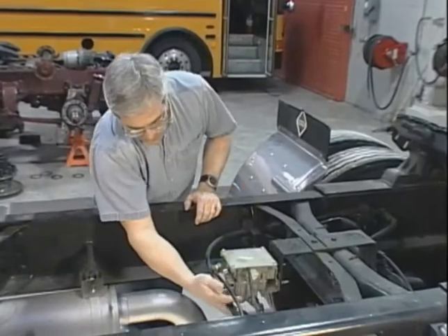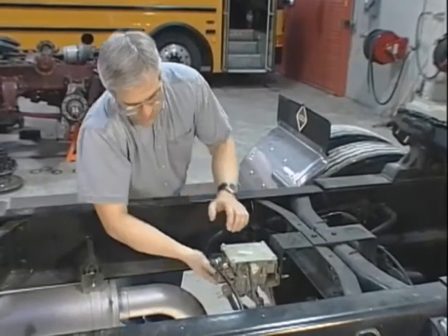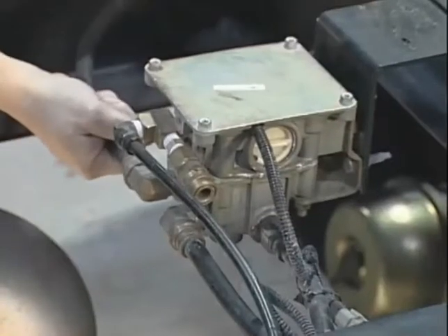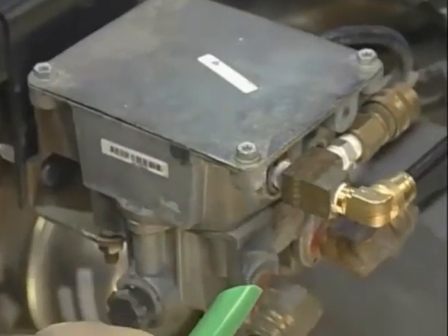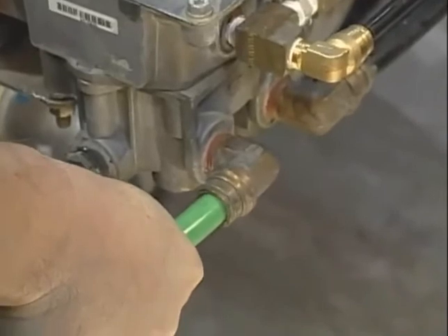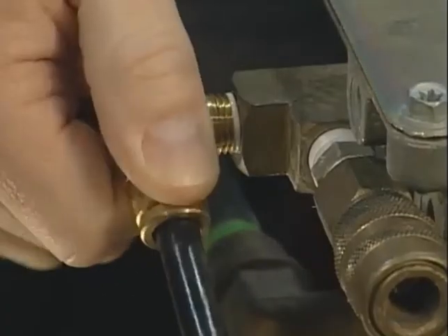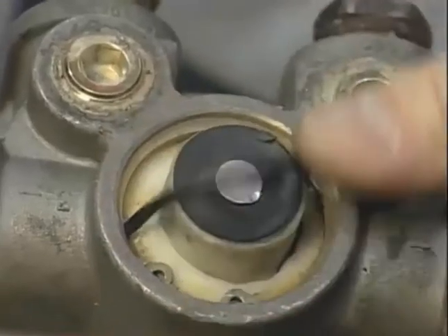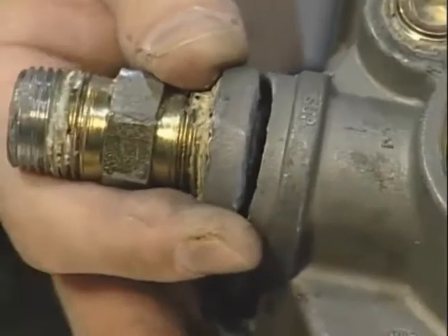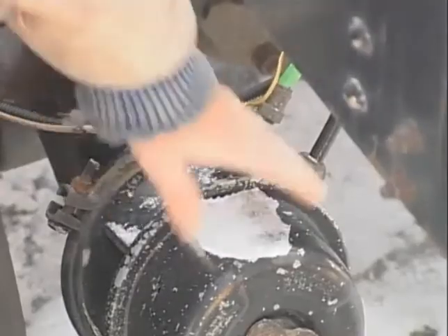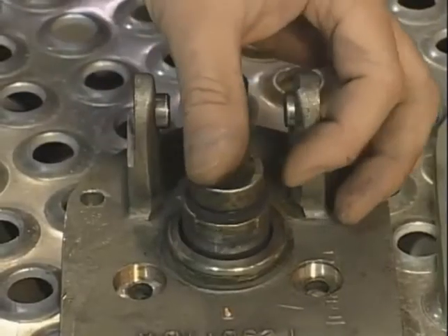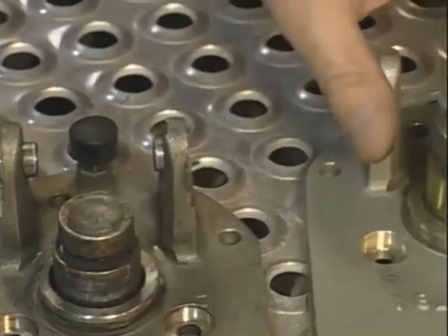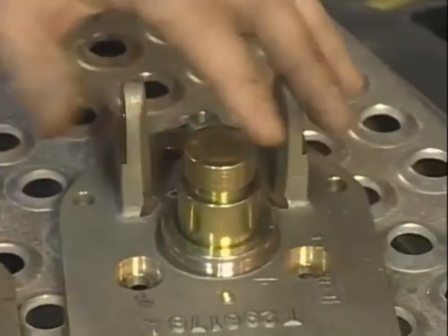It's already been suggested that some air leakage is acceptable by industry standards, but some causes of air leaks may call for further investigation or action. For example, an air leak can be caused by improperly installed components or loose parts like fittings and hoses. It can result from damage caused by accidents or on-road debris. It can be caused by extreme operating temperatures. It can also simply be that system components and devices have worn out and reached the end of their service life.